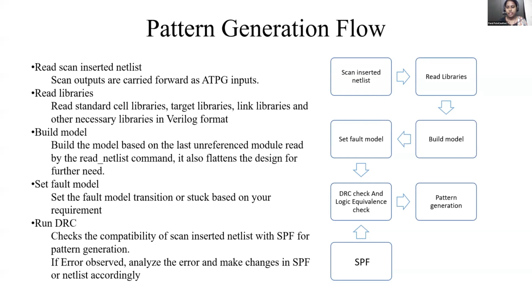Then there will be some DRC checks first, like making sure our clock is not connected to the input of some flip-flop. It's a design rule check that there are no connectivity violations or placement violations, because it's technology dependent, right? We have already fetched some technology file, so we are just checking that after DFT insertion we are not violating any of them. During the DRC check, another input is the SPF, that is, the STIL protocol file. It contains the basic information pertaining to the scan chains and the design.